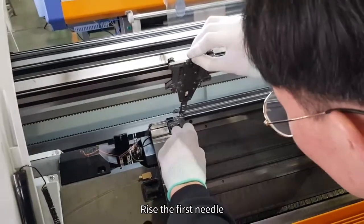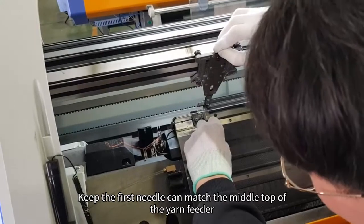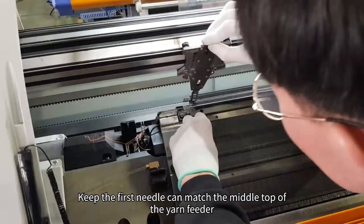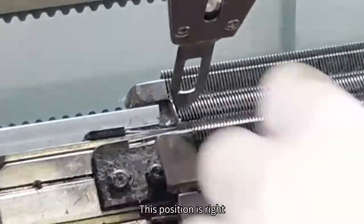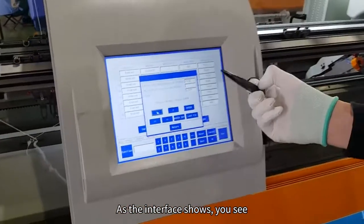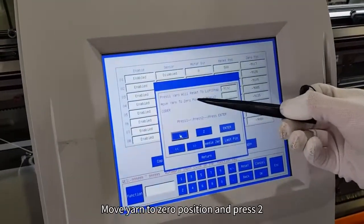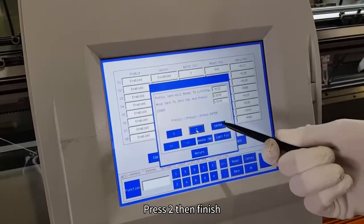Raise the first needle. Keep the first needle matching the middle top of the yarn feeder. You see, this position is right. As the interface shows, move the yarn feeder to 0 position and press 2. Press 2, then finish.